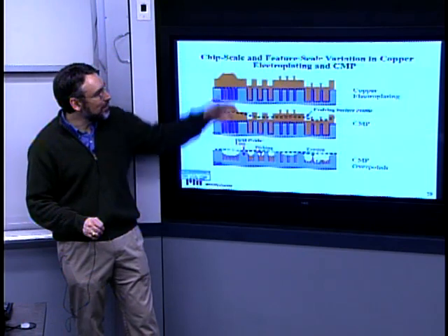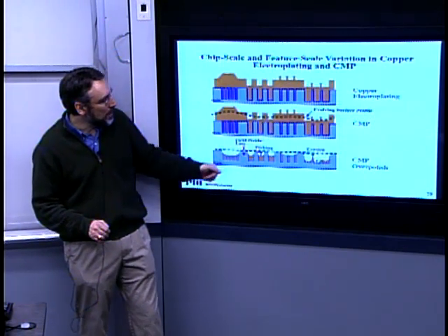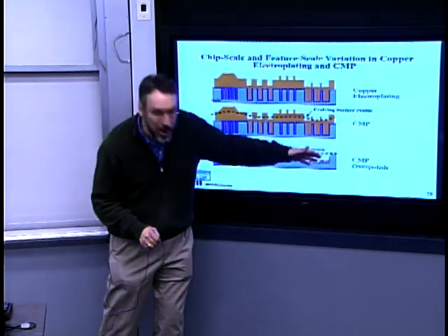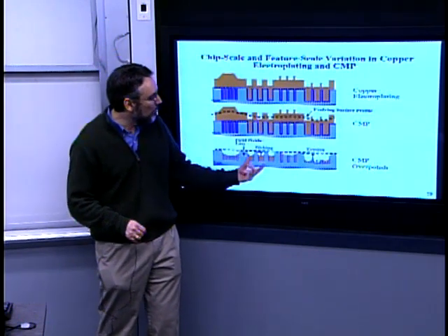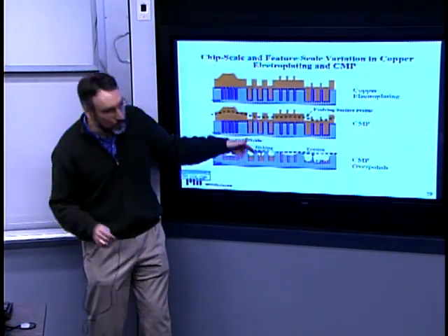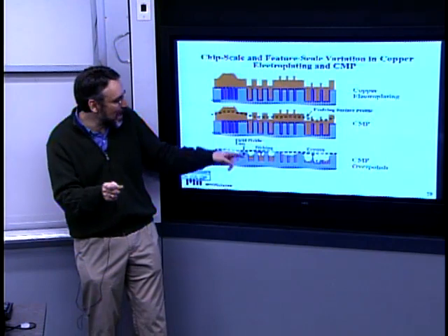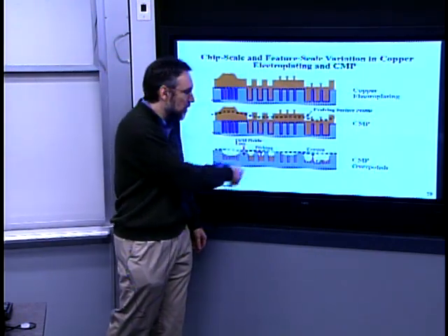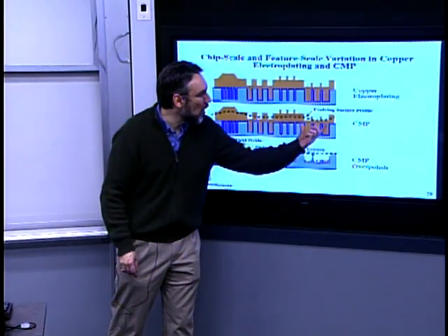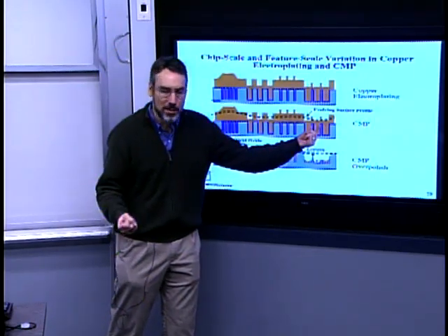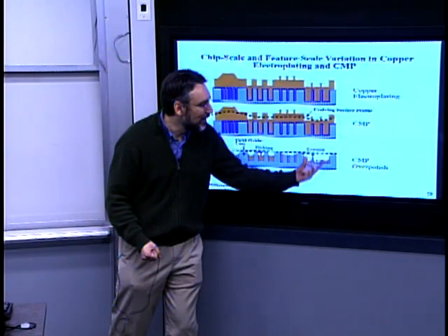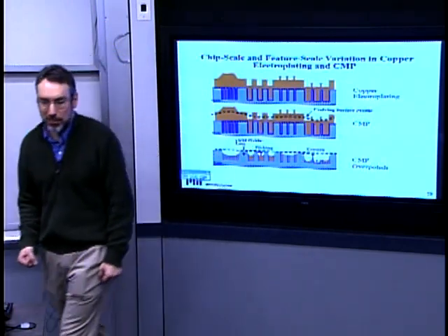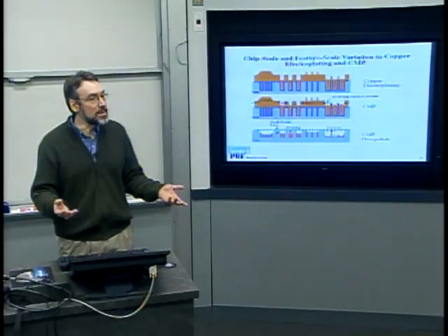But it also has a geometric imperfection arising from over-polish, where big, fat, wide lines, the polishing pad, that polyurethane pad, actually digs down in and over-polishes certain features. And in regions where you've got a lot of copper and very little hard supporting oxide, it actually erodes down appreciably.